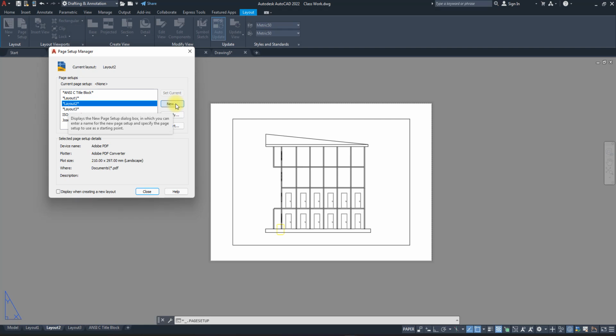But the reason why I don't advise using that is there will be some drawing whereby what you are placing has to be landscape. In the same project, there will be some drawing whereby what you are placing has to be portrait. Do you understand? So that's why you have to create a different layout. So if you know that you want to be consistent with the paper size you want to use, you want to be using A4 all through, you can create two page layouts, one for landscape, one for portrait, and have every setting the same. Am I making any sense?